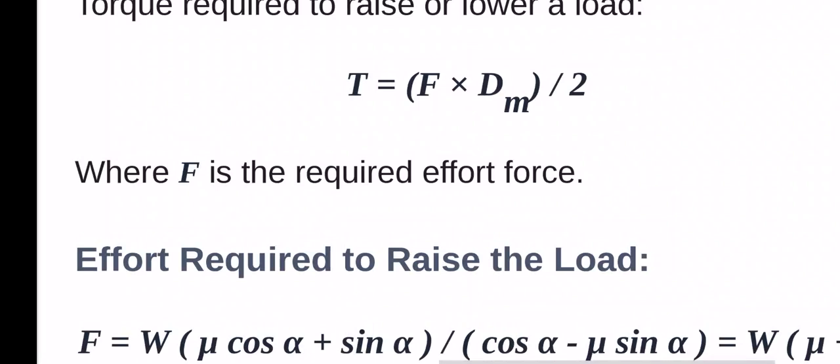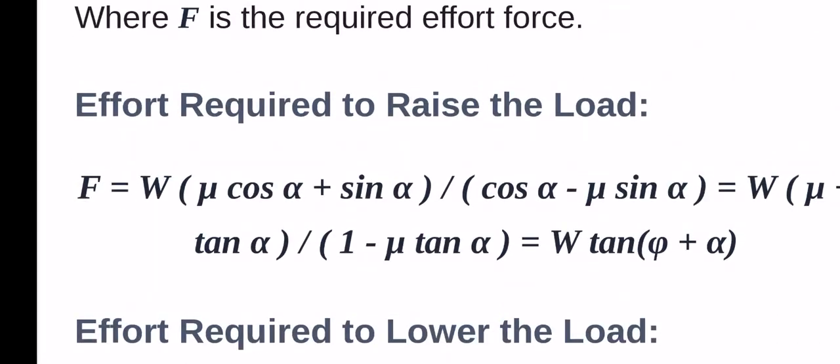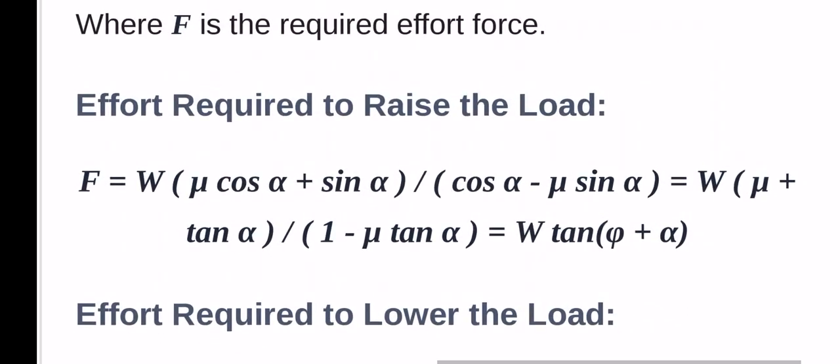where F is the required effort force. Effort required to raise the load: F = W (μ cos α + sin α)/(cos α - μ sin α) = W (μ + tan α)/(1 - μ tan α) = W tan(φ + α).